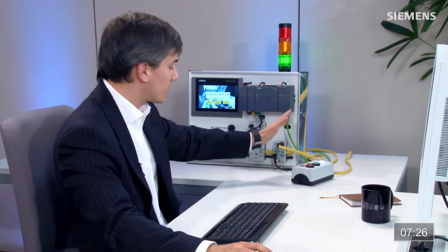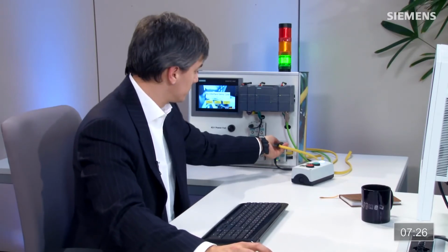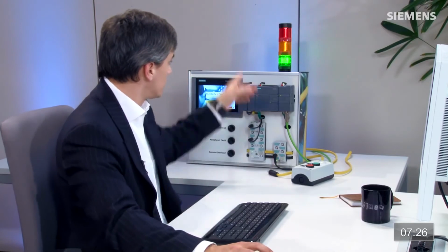All I've got to do now is go here and see I can hit the Start-Stop station. Everything runs the way it's supposed to. And in fact, I can go over and fault out the ASi network. And this is the actual input for our Start-Stop station. It should fault. So the fault logic is working the way it should be. And the beautiful thing about this HMI is I went to Service Support and downloaded faceplates and function blocks for additional ASi diagnostics. And this is completely free of charge.